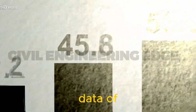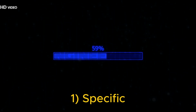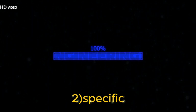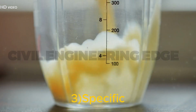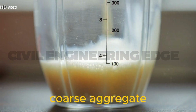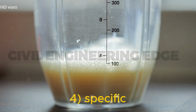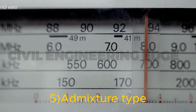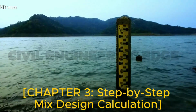Test data of materials. 1. Specific gravity of cement, 3.16. 2. Specific gravity of fine aggregate, 2.46. 3. Specific gravity of coarse aggregate, 2.73. 4. Specific gravity of water, 1.00. 5. Admixture type, super plasticizer.